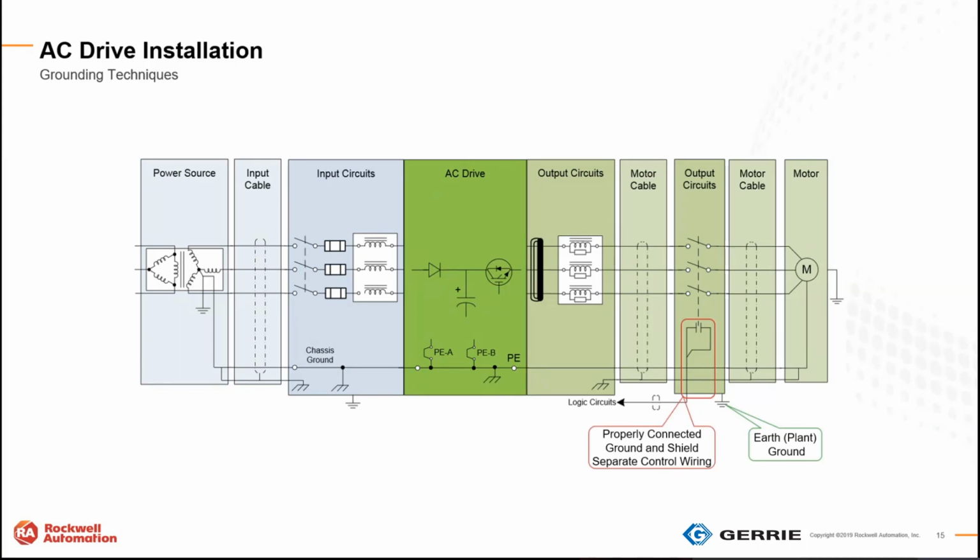So, a remote motor disconnect. It's housed within its own steel enclosure near the motor. The enclosure is typically bonded to the plant ground, but the cable from the drive enters the box and another cable exits the box. It's important to ensure that the cable ground conductor is continuous through the box and just not connected to the ground conductor on the box chassis.